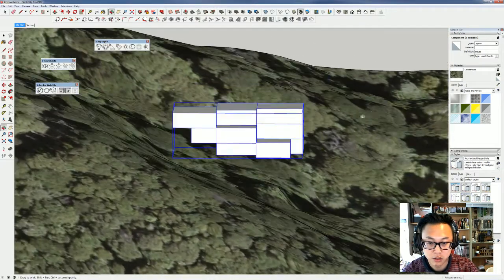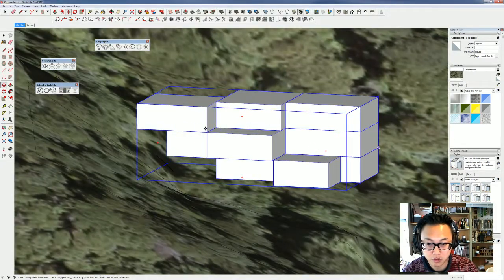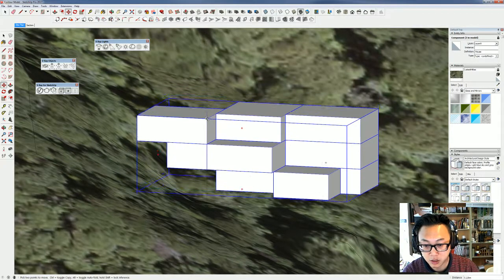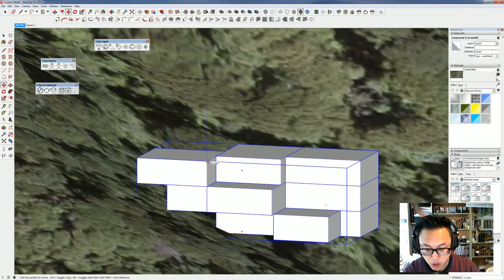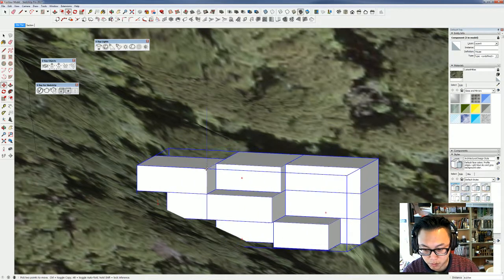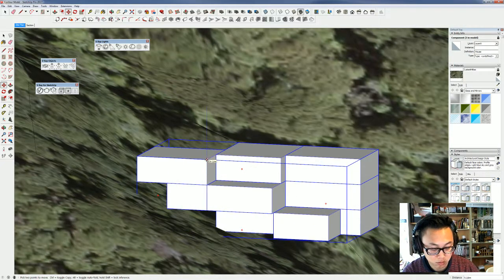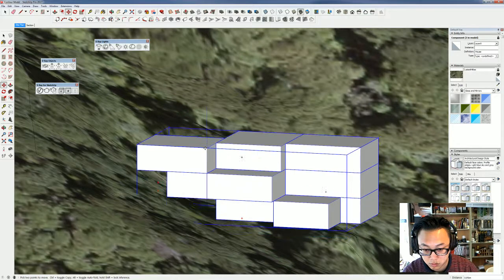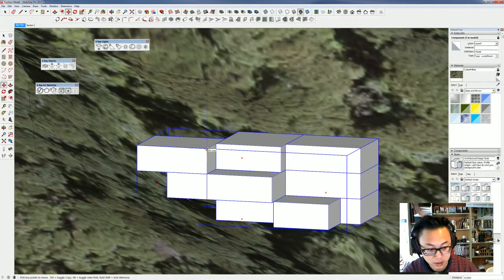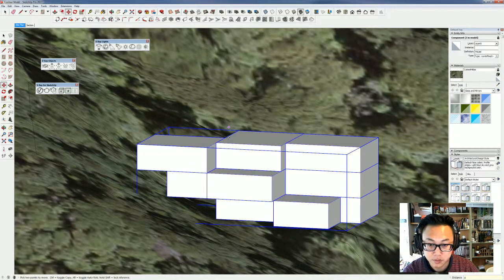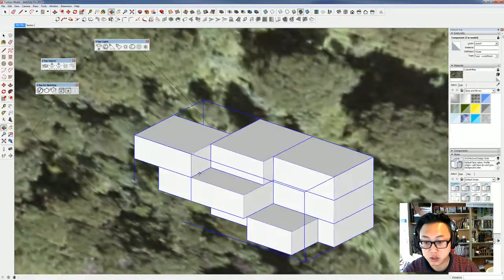And then I'd like to drop everything down, so I can make another guideline, but now using that vertical as a reference. Double click so it will create on the exact same spot. Press M and start to move everything down. Just want to make sure that I'm not going below the contour, so maybe I'm gonna drop down, let's say, 4 meters.